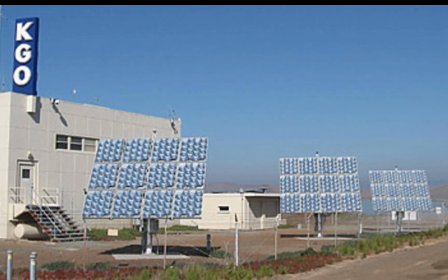This is a concentrated PV system that I drive by a lot. It's on a bridge called the Dumbarton Bridge in the Southern Bay Area, if you're ever there. And one of the things that I notice about this is these trackers, they don't aim in the same direction most of the time. They're aiming in different directions. That means that this is not working because concentrated PV needs to focus and aim straight at the light. If you had regular PV and your tracker broke, you'd still be getting production. With concentrated PV, you would very rarely get any production because you need to focus those light beams. Concentrated PV is neat, but it's just not common anymore.